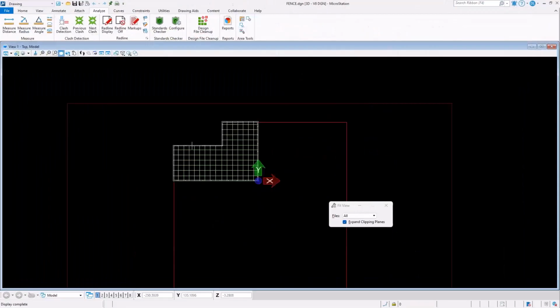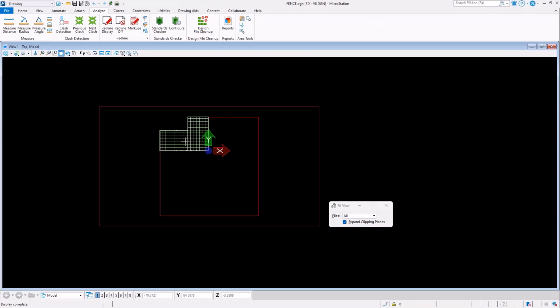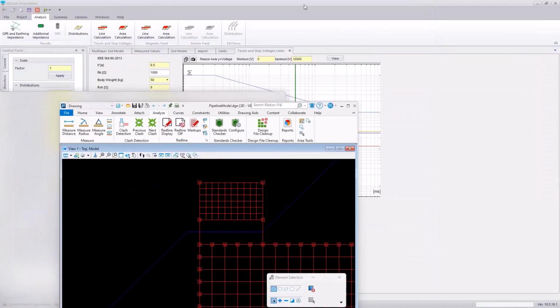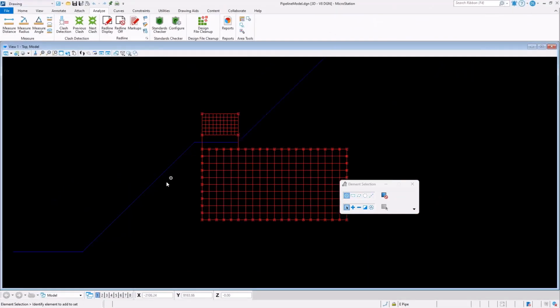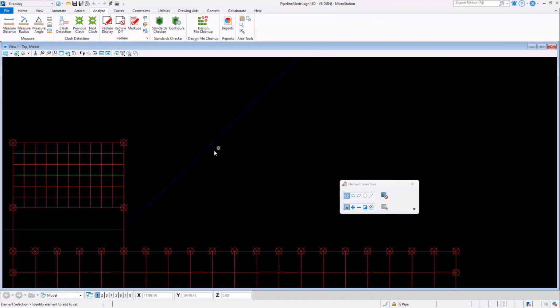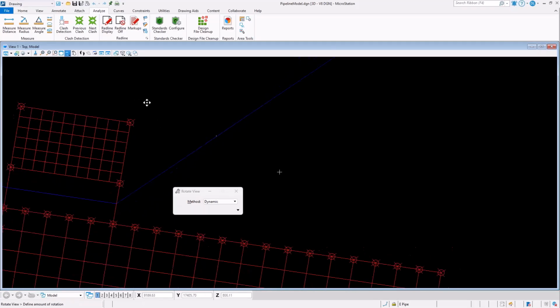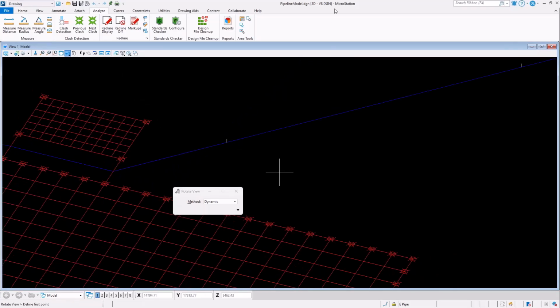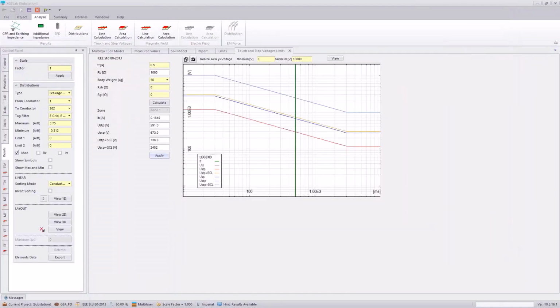We're also going to look at transfer voltages to a fence line, perimeter fence line. And if we have time, I'll look into a transfer voltage from a substation to a pipeline, particularly looking at appurtenances or test valves coming off of that pipeline. So we do have 3 different case studies that we intend to walk through this morning.